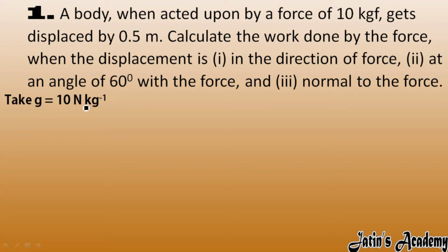Now we have to calculate the work done. So we need force and displacement. Force is given as 10 kgf. First we have to convert 10 kgf into Newton, so multiply with g, 10. So here we got 100 Newton. So force is 100 Newton and displacement is 0.5 meter.